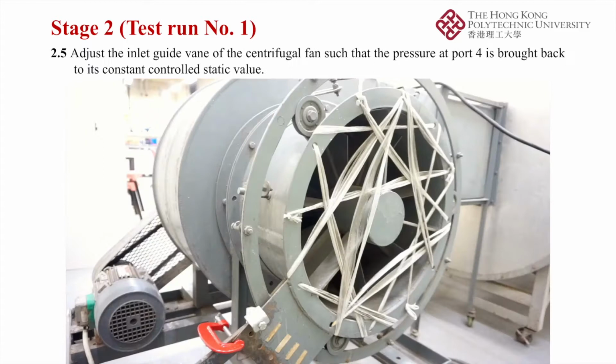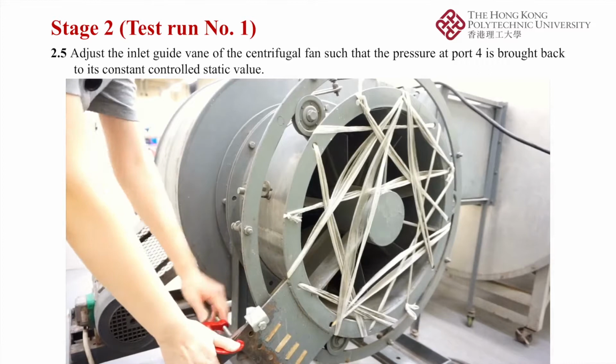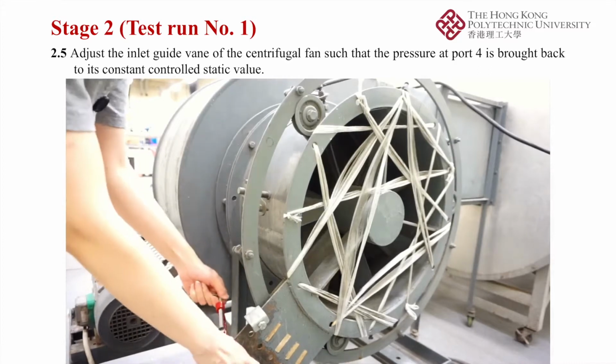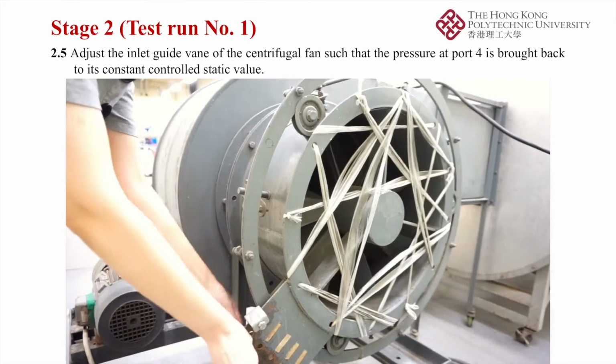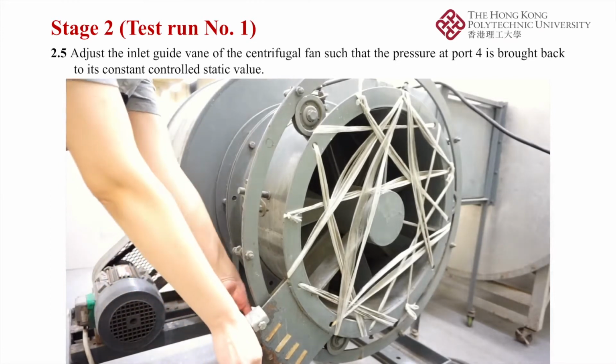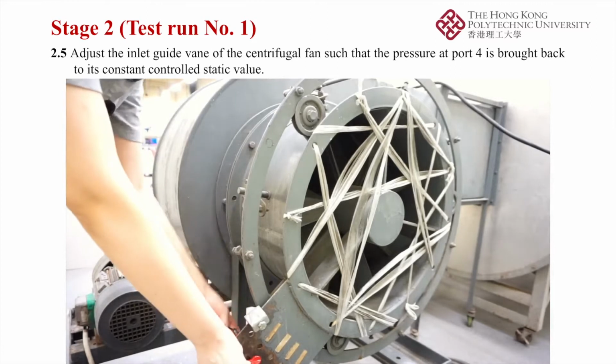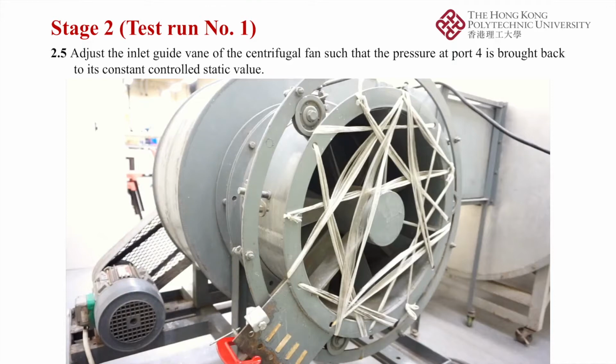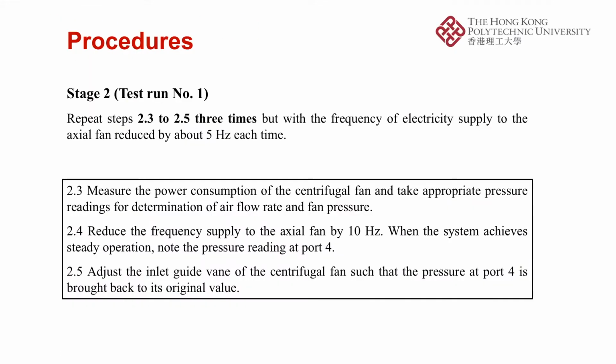After that, adjust the inlet guide vane such that the pressure at port 4 is brought back to its constant controlled static value. Next, repeat steps 2.3 to 2.5 three times, but with the frequency of the axial fan reduced by about 5 Hz each time.